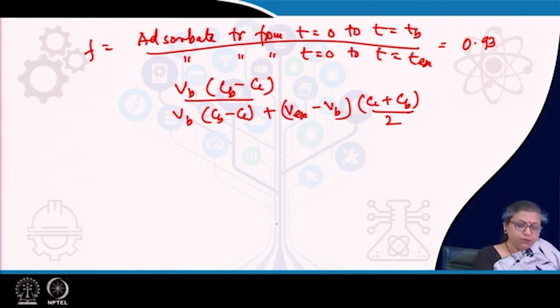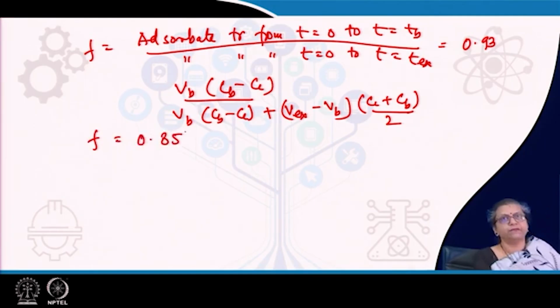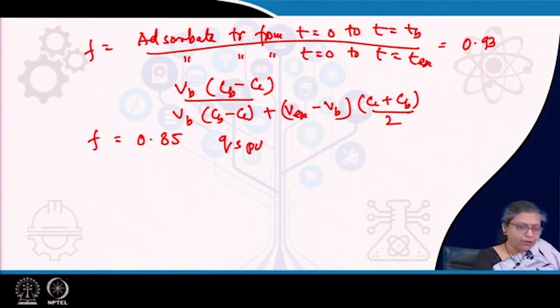So, therefore, for the actual plant, what we do, we assume the F to be equal to 0.85 and we proceed, because naturally when the adsorbent bed starts operating, and also due to other uncertainties, a little amount of maldistribution in the larger bed, the F utilized will naturally be much less. And after that we also find out the adsorbent loading in the pilot plant.